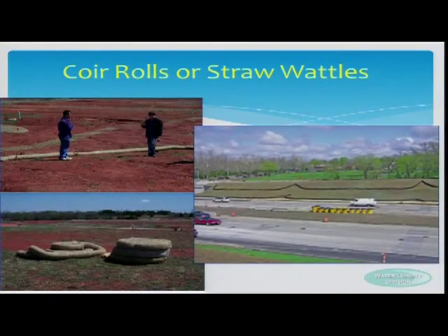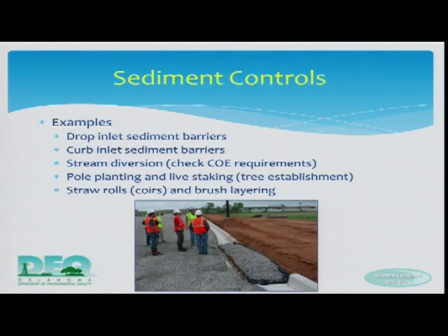You'll see straw wattles installed. Remember that you've got to trench those in properly and stake them down so that they'll work right for you. They do a great job when they're installed properly. Drop inlet controls, curb inlet controls. There are a lot of different innovative techniques that I've seen used by people out there. Think about your site. Think about traffic.